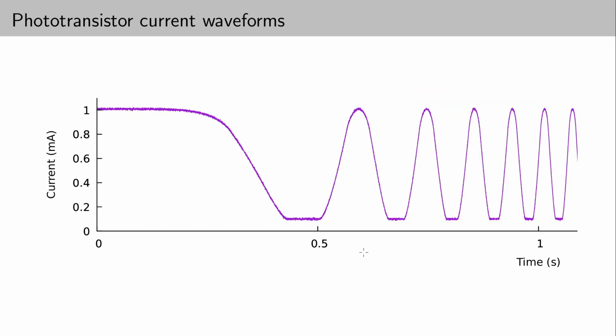And in the whole of this simulation that I did, the motor encoder disk starts from rest, accelerates to a constant speed, and then decelerates to rest again. And you can see that I've added a little bit of noise, and that the current doesn't go to zero. I've taken a very, very conservative value for the true dark current of 100 microamps, which is huge. It's going to be way more than reality, but it's a very conservative estimate.